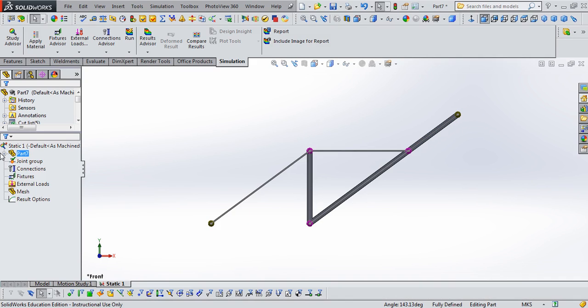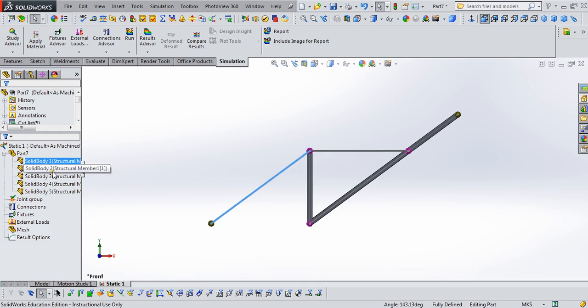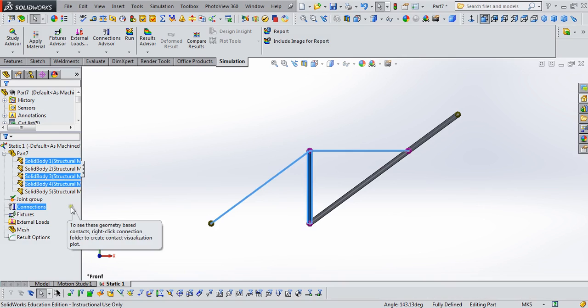structural members. If we open up this part, now this may say cut list or structural parts, but you can open it up and you'll begin to see all of the different pieces. They all default as beam elements. Now a few of these we want to define as truss elements because we know that they are two force members. So let's select these two cables, just the cables. I'll have the control button down, and then there it is, 4.